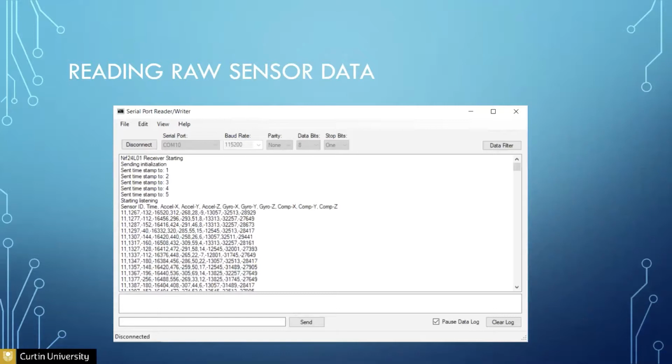Connect that to your micro. Just send a single character through the Bluetooth sensor, and then you also need another Arduino connected to your laptop, with another Bluetooth sensor connected to it. Now, what you're going to end up doing is you send the information from your sender to the sensor that's connected to your laptop, and then you can use this program that I'm using.